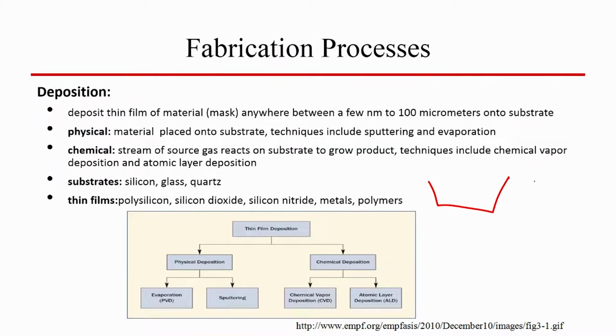I cannot use this technique where I am heating the material to its melting point, because the holder will also get melted. So what I have to do is go for another kind of deposition, called electron beam deposition, where the heating is done through the electron beam. The container that holds the source material is called a crucible. In case of thermal evaporation, it is called a boat. If you see this slide, this is a boat in thermal evaporation.